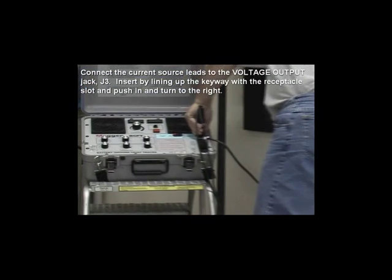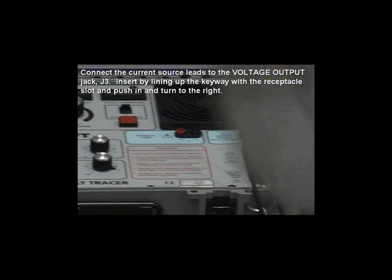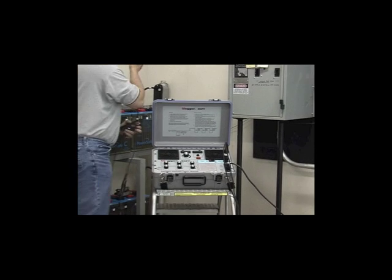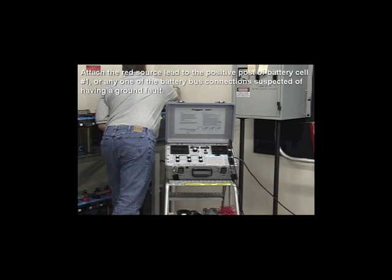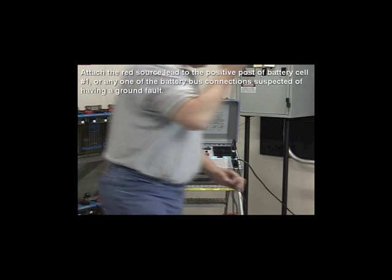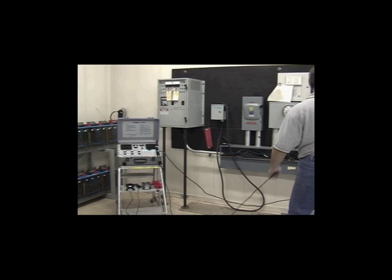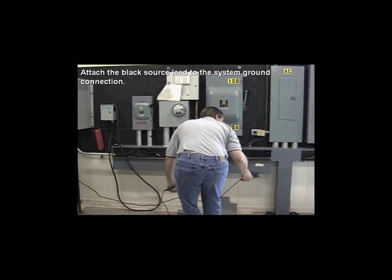Connect the current source leads to the voltage output jack J3. Insert by lining up the keyway with the receptacle slot and push in and turn to the right. Attach the red source lead to the positive post of battery cell number 1 or any one of the battery bus connections suspected of having a ground fault. Attach the black source lead to the system ground connection.